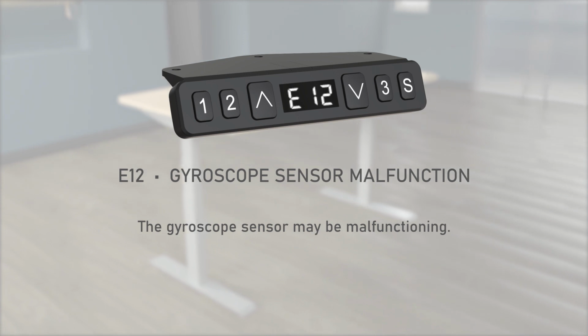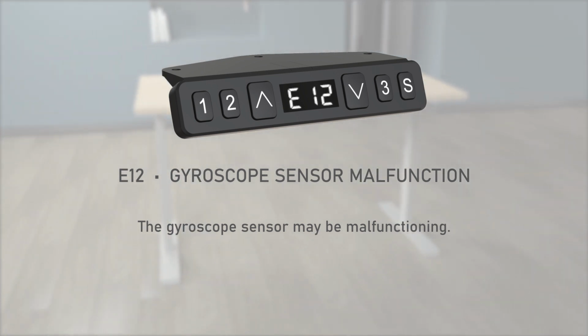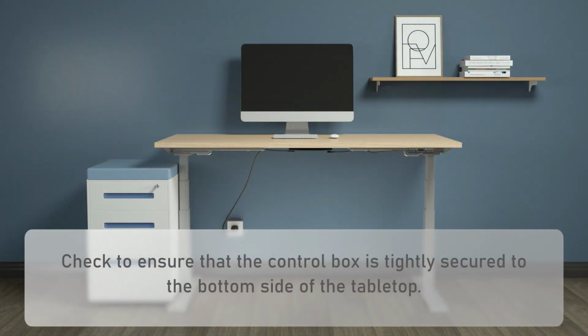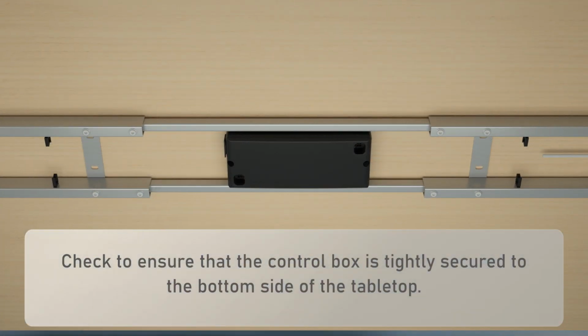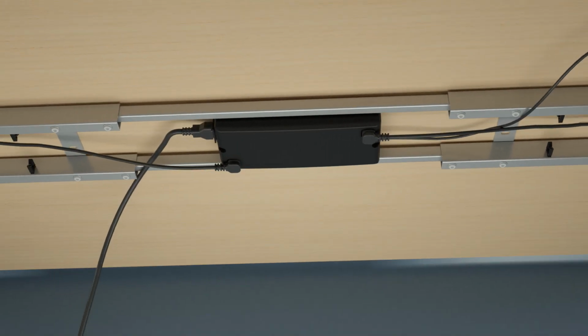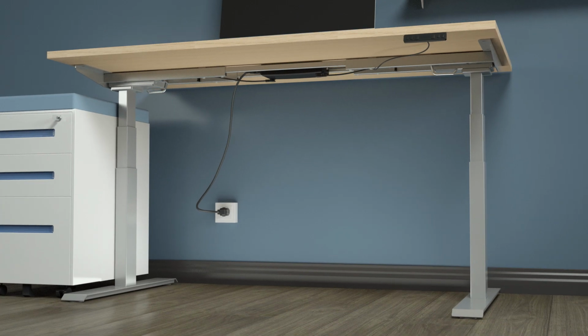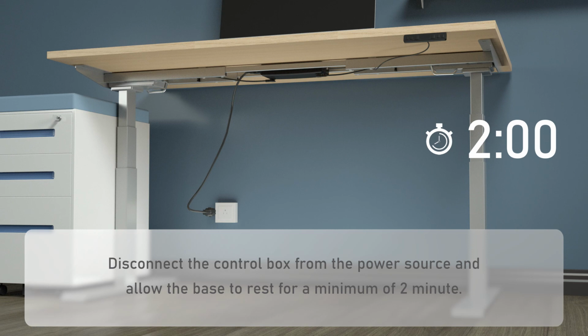E12, gyroscope sensor malfunction. The gyroscope sensor may be malfunctioning. Check to ensure that the control box is tightly secured to the bottom side of the tabletop. Disconnect the control box from the power source and allow it to rest for a minimum of 2 minutes.